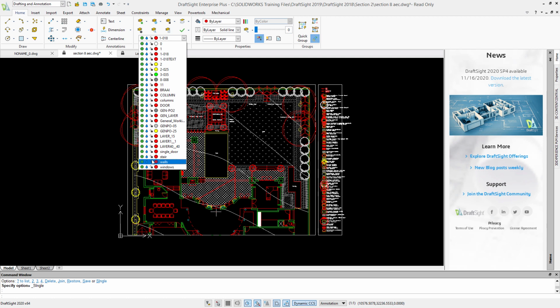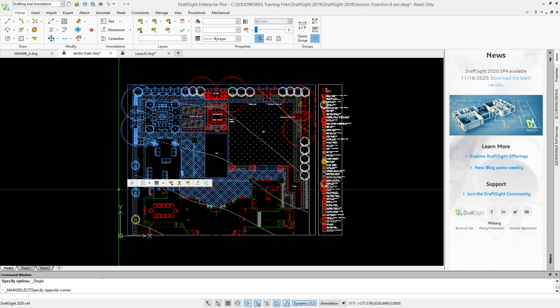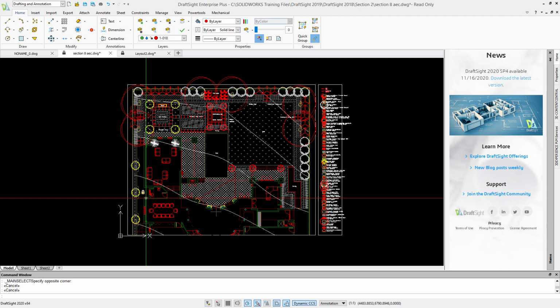If we're concerned about amending a layer that we don't want to amend, then we can lock it using the padlock. Now I will not be able to manipulate anything on those layers. I get a little padlock if I try and hover over as if to select anything.